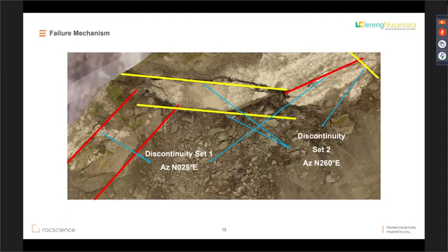So how come this happens? Well, the landslide occurs near the geological fault axis. The geological fault is formed by compressive force. And as what FGBL said in his book, there are generally three different joint sets that might occur in the axis of this fault.